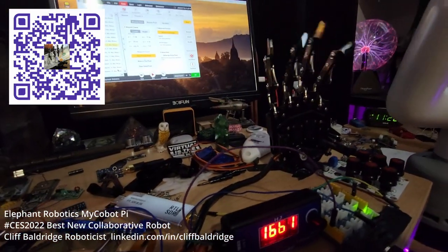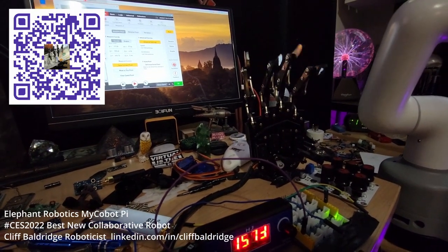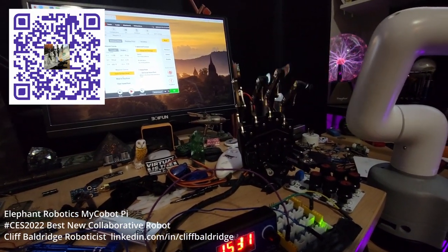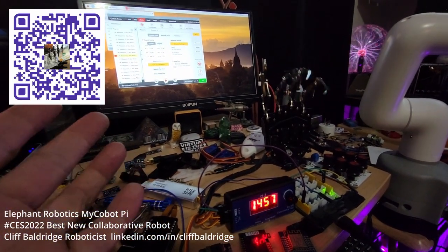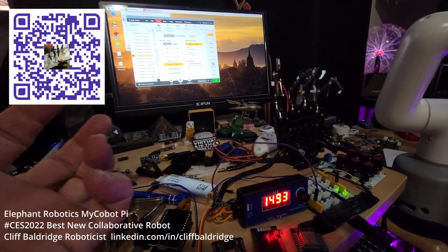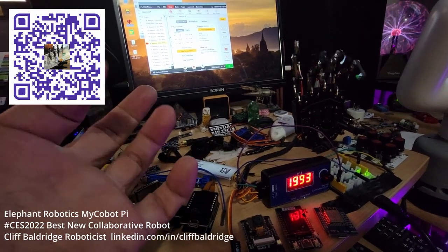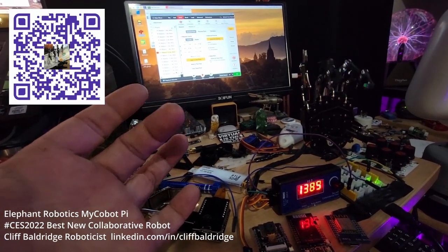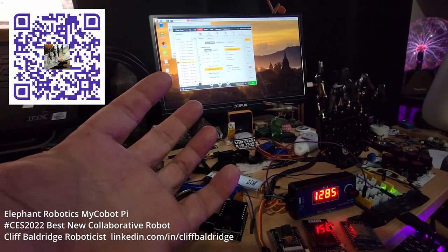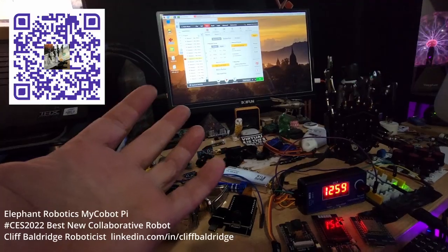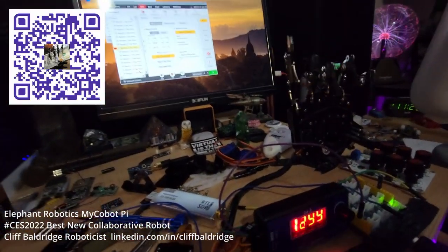The problem with the power glove and those ribbon sensors is that those pressure sensors are going to cost about $20 per sensor. So to have a long flexible sensor for each finger at 20 a pop, so 20, 40, 60, 80, it's going to be $100 to have 5 flex sensors. But when I have these flex sensors, I can attach them to a glove, and then the flex sensors will be able to control the robot hand.